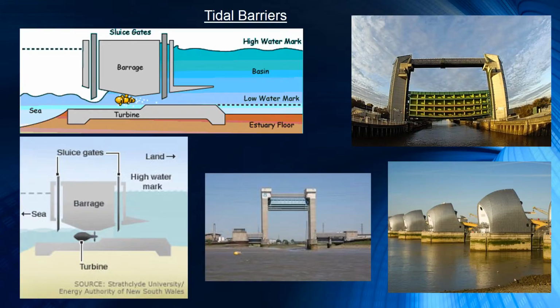This flow of tidal water back and forth causes the turbine generators located within the tunnel to rotate in both directions, producing electricity. However, this two-way generation is generally less efficient than one-way or ebb generation, as the required head height is much smaller, which basically reduces the period over which the normal one-way generation might have otherwise occurred. Also, bidirectional turbine generators designed to operate in both directions are generally more expensive and less efficient than dedicated unidirectional tidal generators.